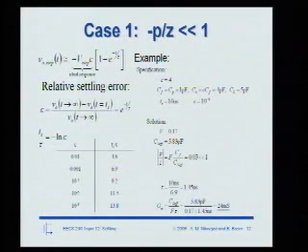If you compare this with a linear settling time, let's say that settling time were a ramp function, and you wanted to get 10 times more resolution. How much longer would you have to wait? Obviously 10 times as long, right? But over here, if you look at the numbers, if I want to go from 10 to the minus 3 to 10 to the minus 4, I only have to wait a couple more time constants, from 7 to roughly 9. So that's actually very nice.